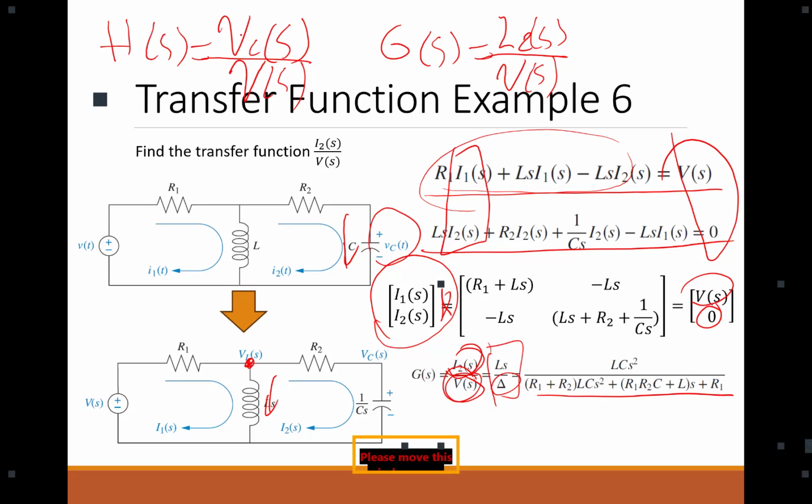Let me give you an example. When you work with a capacitor in industry, one of the most important aspects is transient voltage. When you switch or any transient activity happens in your circuit, it creates a voltage surge, which is a very short, high voltage peak added to the steady state voltage of your capacitor.